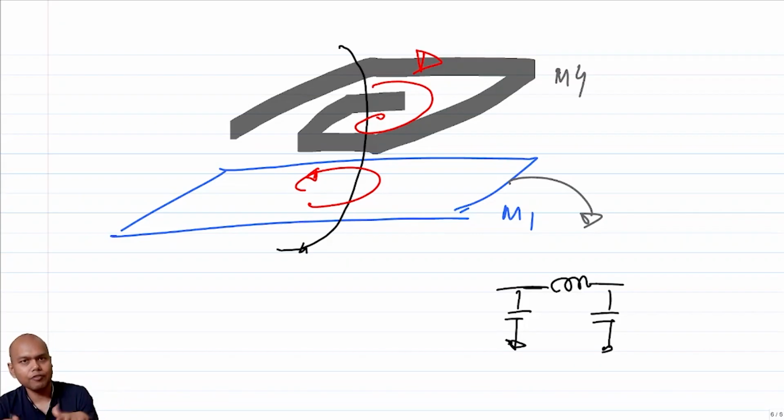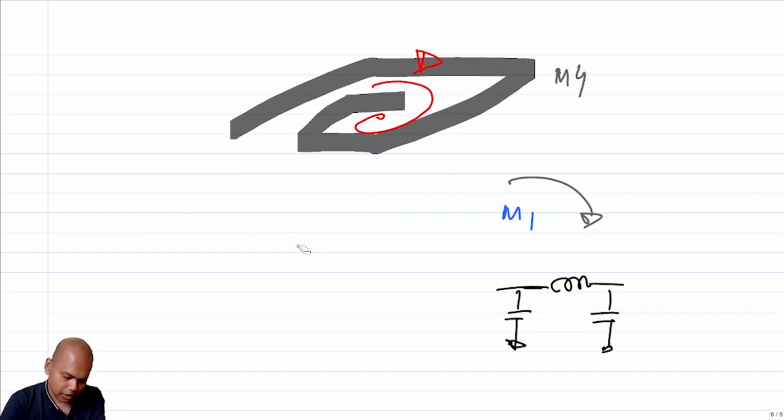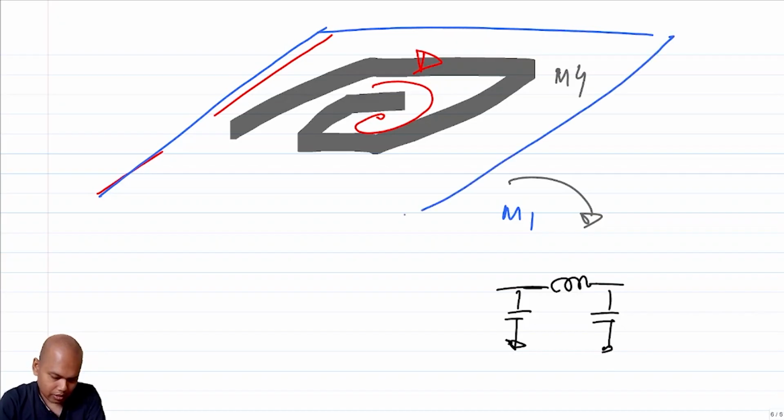The effective inductance itself will go down, right? Forget about the loss. So you cannot really do this directly. What people figured out were smart ways of doing it. If I want to reduce this loss, what I can do is, instead of giving a continuous strip of metal, I can break the metal into multiple strips. So you can now assume that underneath, it's not a continuous strip of metal. Here I will break the metal into small strips.